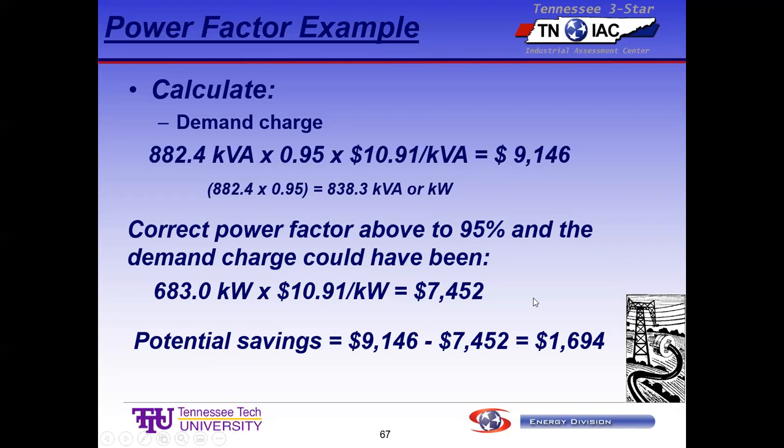The other small piece is that you will also pay for your line losses, your I²R losses, because that extra current flowing through your wires is going to heat them up a little bit more. That's probably on the order of 0.5%. It's small, but it's there. This is a bigger presentation, and I'll send it to you too. There is a slide or two in here that does a little calculation to estimate that extra bit, but I didn't throw it in this example, I don't think.